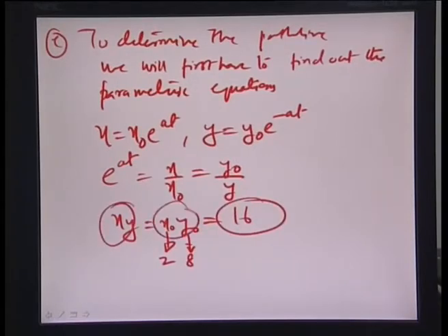So, therefore, what we find out here is that by definition what a path line means is the location of the particular point at a certain time instance. So, if you want to join all such particles which have moved past a certain point, you have to make them independent of time, and in order to make them independent of time you find out the equation, which has come out the same as the equation of the streamline as before.